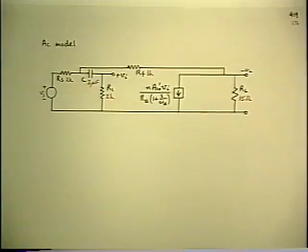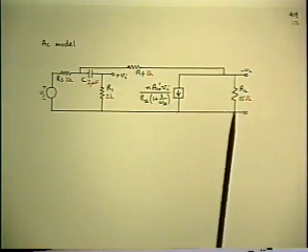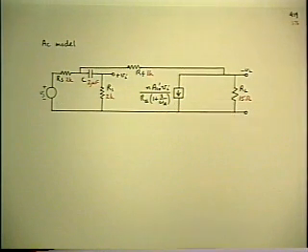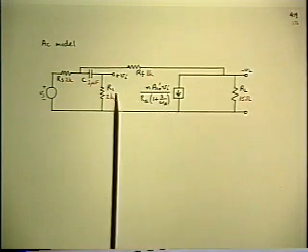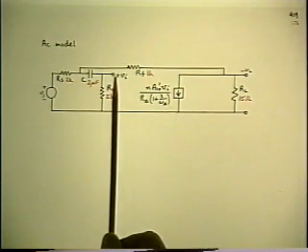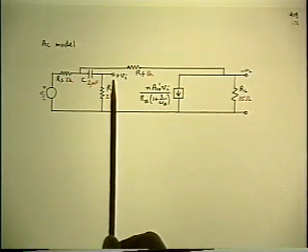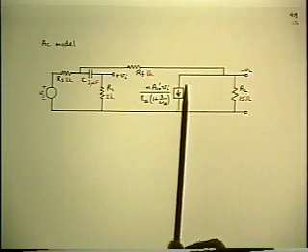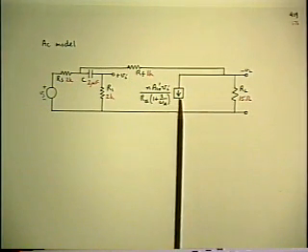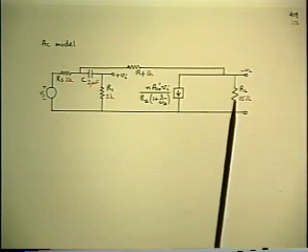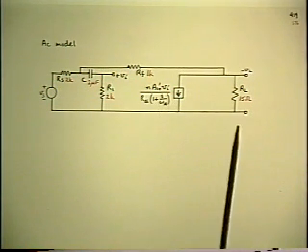Well, we're talking about the analysis for the loop gain of an elementary little audio amplifier. This is the equivalent circuit model that we're working with, having stripped it down to the bare essentials. Notice that the forward path is now all the way down to an input voltage being applied to an infinite input impedance of the forward path, and the output of the forward path is represented only by this current generator. So you can't get much less in the model of the forward path. Everything else is external.